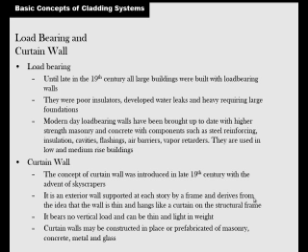So, the basic concepts of cladding systems: load bearing and curtain wall. Load bearing: until the late 19th century, large buildings were built with load-bearing walls, really stone or masonry walls. They couldn't make them very tall, because then you would have to have such thick bottom walls that it's hardly worth it. So it probably limited them to 4 or 5 stories in reality. Plus, you didn't have elevators, so you didn't want to walk up that many flights anyway.